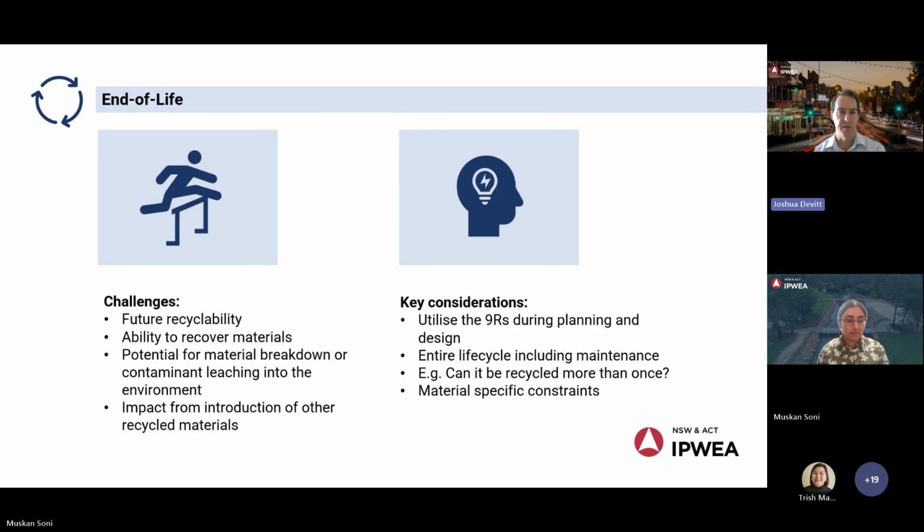Okay, and then end of life. Obviously the focus here, given that we're talking recycled materials, is the recyclability of these materials. So what happens when they hit end of life? How can you repurpose them and use them in another cycle? Can they be put back into the same road pavement? Can they be used in another location or for other purposes? I think that's one of the key considerations, and really that key mind shift is to think about not putting things in the road now that are going to create issues down the road, as I mentioned earlier. So that's a really critical piece that people need to keep in mind when they're using these sorts of materials.